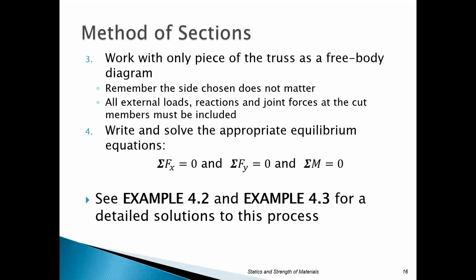Choose the one, in my opinion, that has the least amount of forces, because then it just makes less work. You don't have to worry about as many forces in X, Y, and moment. Okay. But you have to make sure, and this is critical, you add all the external loads and reactions that occur on that section. Some people will try to add other forces, or they delete them. If you do that, of course, you're screwing it up too. And the only thing you're solving are joint forces that occur at the cuts.